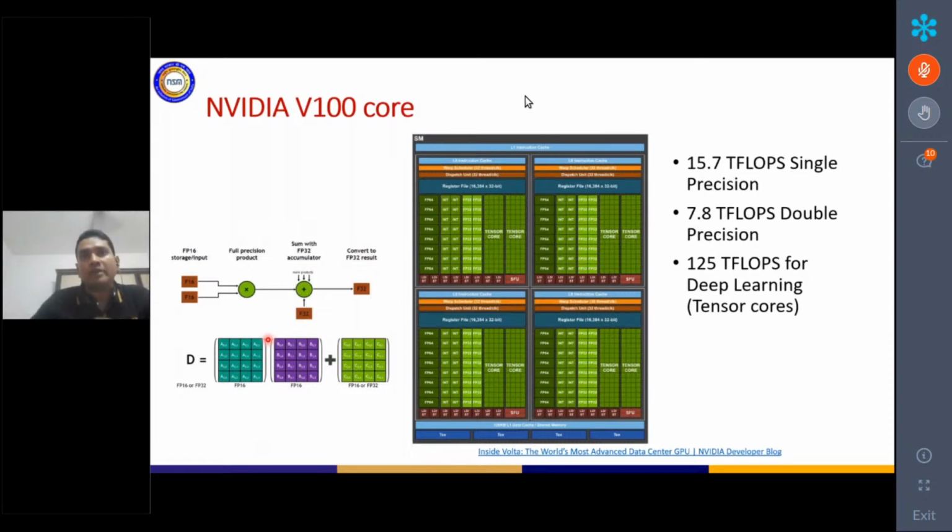So if you have a matrix multiplication unit inside your SIMD, you can perform the entire tensor, a set of input data. Basically you can take these two sets of data, 16 cross 16, plus you can accumulate another 16 which is already there in the accumulator, and you will get the entire 16 data.